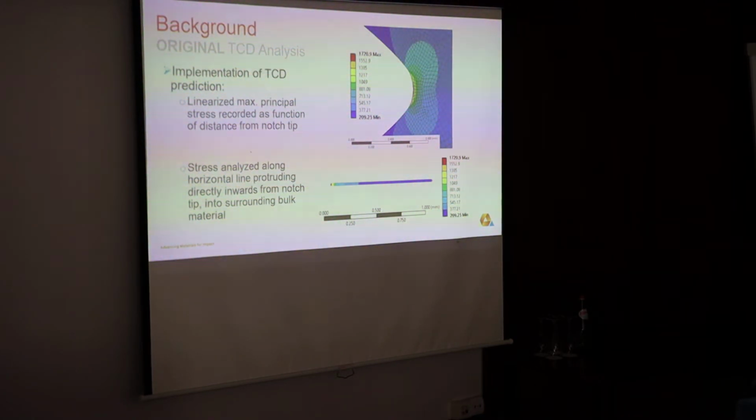A previous study which we conducted prior to this one involved the fatigue prediction using TCD methods on additively manufactured notched titanium-64 material, which included us considering the scenario of a rough SLM surface finish being modelled as a micro notch for the purpose of making TCD-based predictions on the micro stress concentration level, whereby we considered a rough SLM surface finish as a small stress concentrated feature.